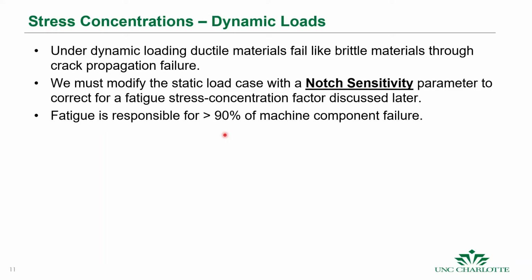Okay, and so we have to consider the dynamic loading, and in practice, more than 90% of machine components fail due to fatigue. Okay, and I know we focus a lot in the undergraduate program on statics and static failure and calculating the stresses, but it's not enough. Okay, so it's in this class where we talk about fatigue failure, and fatigue failure accounts for most machine component failures in all machines. Okay, and it's like $100 billion cost for the United States in like 1980s dollars. It's a big deal.